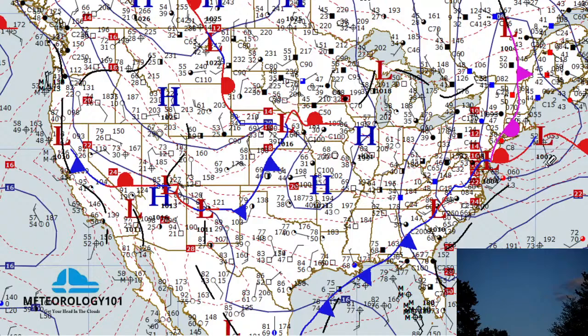So you can see what your wind speeds are, what your thermal advection is, and when to forecast these low ceilings. When you get into those red IFR conditions, you want to know when those conditions are going to start, where that front is, how close it is, how fast it's moving, and when it gets into your area, you got the overrun that is going to cause those low ceilings.